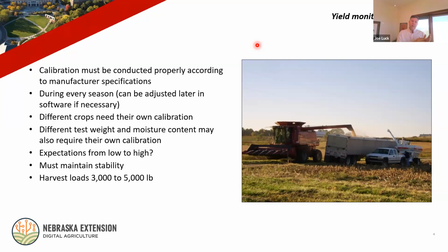So the flow through the machine is going to be pretty low. What are your expectations of a really high flow through the machine? And so, best yielding crop, moving at your typical maximum speed, what does the flow through the machine look like? And if we're doing a multi-point calibration, which is typically what we recommend, we try and span that range somehow with our different calibration loads.